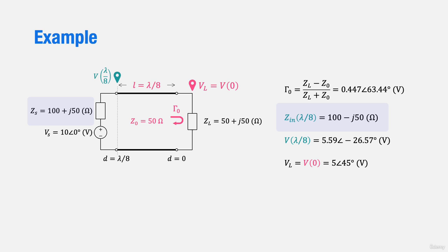So on the bright side, although the transmission line effect alters the load impedance, it is not necessarily a negative outcome. In fact, we can use the line to adjust the load impedance to achieve conjugate matching, which is crucial for maximizing power transmission. As a result, the transmission line is considered an essential component and an effective tool for impedance matching in high-frequency circuit design.